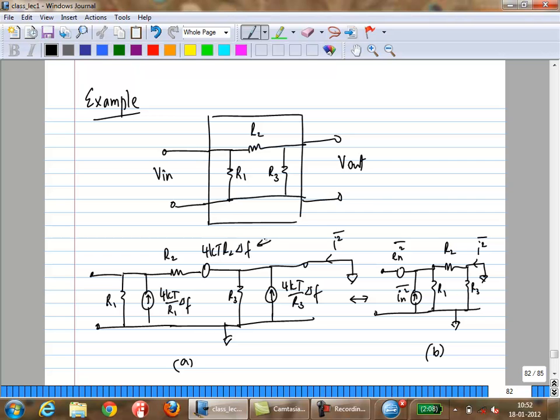But generally, you can't add power. Which is why, when you're keeping track of the correlation, you assume a certain direction and a certain noise voltage and noise current rather than noise powers. Then you can add and subtract the voltages. The square of that will be the overall noise power. It's just En versus En squared. One of them is the root mean squared, the other is the mean squared.